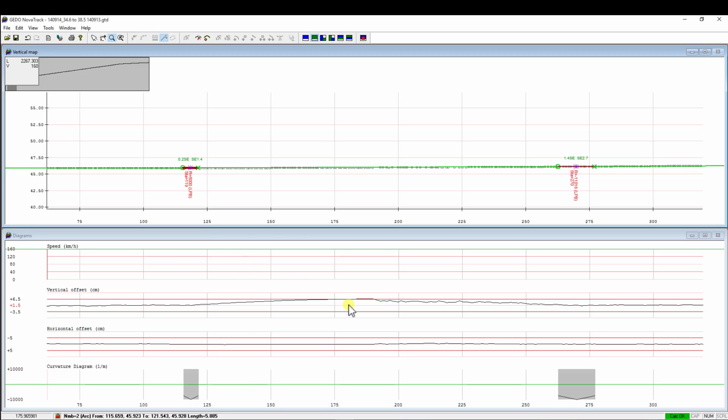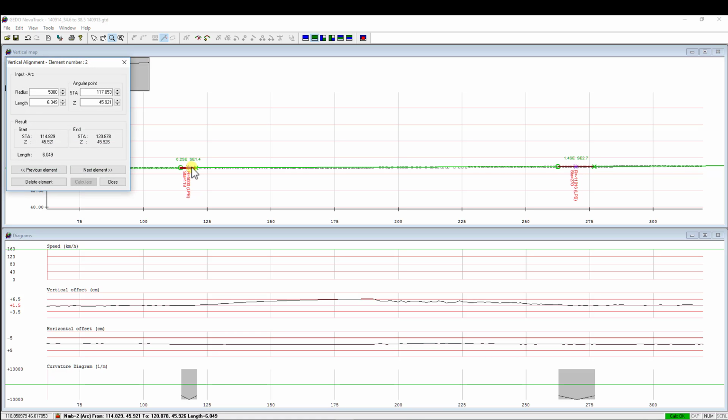The next thing you might want to do is to continue adjusting. So if you double click on the element, you can adjust the Z value, which is actually the elevation, moving the element down or up. Important to know, if you set in the constants that you expect a minimum uplift of 15 millimeters, the software, when you insert a new element, tries to push the element to this desired level.